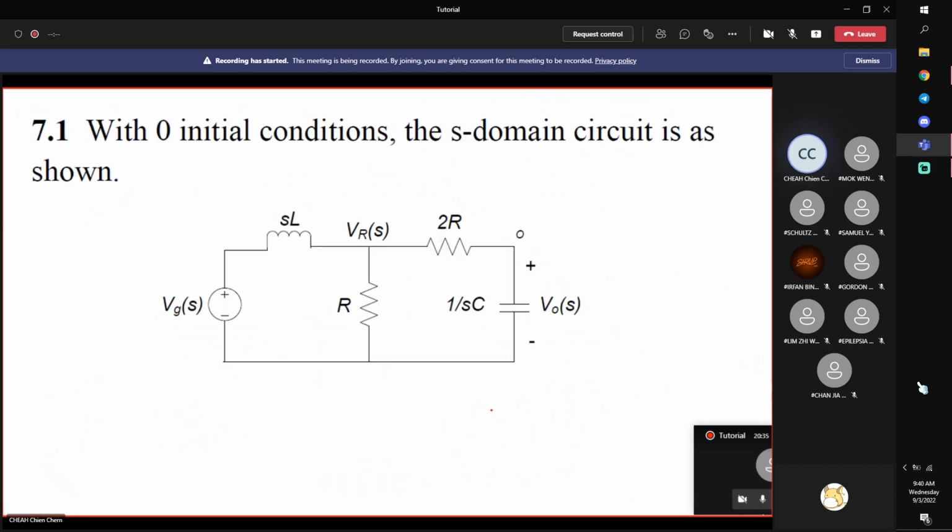Once you transform your circuit into S domain, the relationship between voltage and current will be a linear relationship like Ohm's law, which means that you can analyze the circuits as if they are a resistor network, but of course, it's in Laplace domain. So after solving what you want, you still need to take the inverse Laplace transformation. This is the idea.